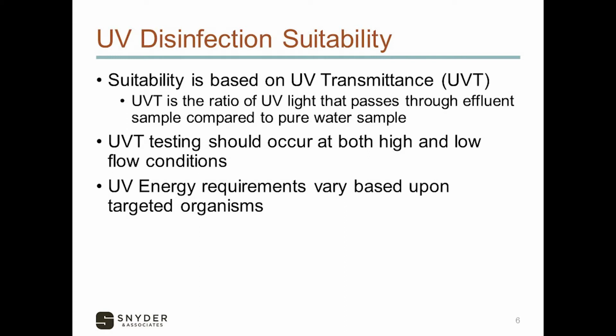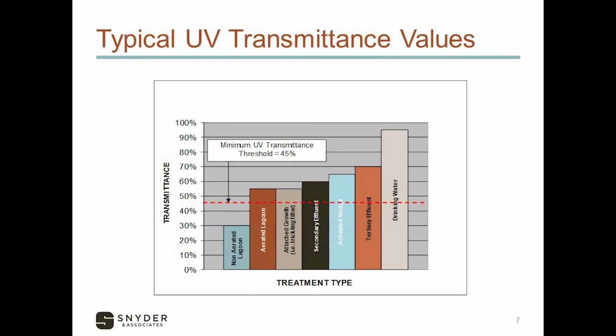And Cryptosporidium for a 2-log effectiveness is about 330 milliwatt seconds per square centimeter. That's kind of an odd sort of units, but remember that number, 330, because in a minute we're going to talk about what we really dose things with. And you'll notice that's the highest one on the list. How does that relate to my process?